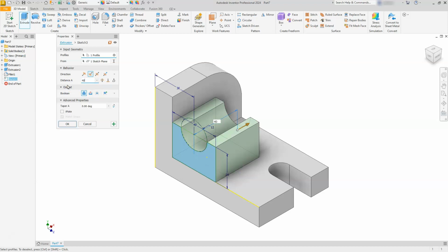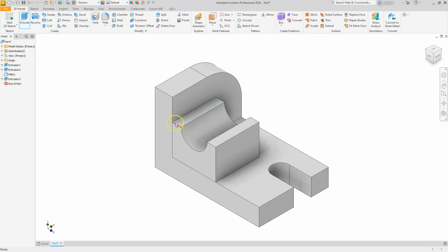And now we're at the point where we have to decide: do I want to have this as part of my other one, or do I want to have it as a totally new solid? In this case, we're going to choose the new solid option. That option is just by clicking this icon here. Once I click this icon, I'm going to hit OK. And you're going to see that it leaves a line between them, right? So this is now an independent solid from that one. If I wanted to move it or do some other things to it, I do have those options.